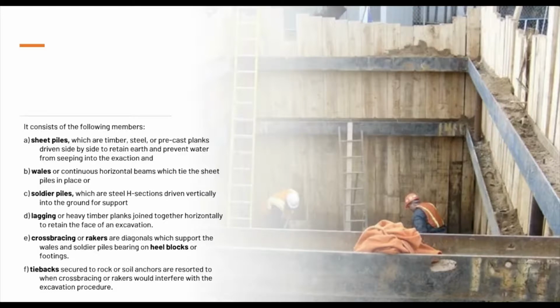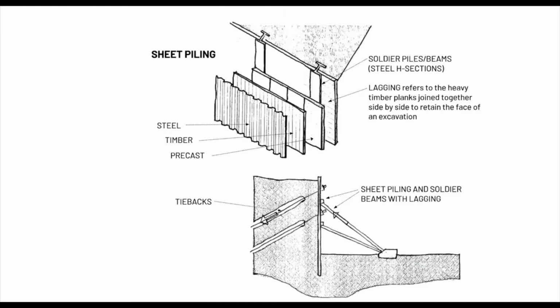Another image of it. Wales are continuous horizontal beams which tie the sheet piles in place. So, ayan. On a more detailed drawing, this is your sheet piling. Lagging refers to the heavy timber planks joined together side by side to retain the face of an excavation.